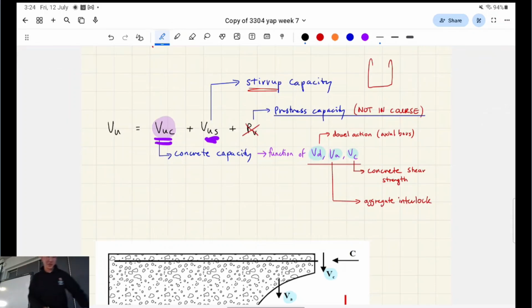So again, shear action. Shear action is like this, right? You're stopping the concrete from slipping along its slip plane or diagonally, like that. The aggregate interlock is that friction from the aggregate scraping against itself, and that'll contribute to the strength of that concrete, right?